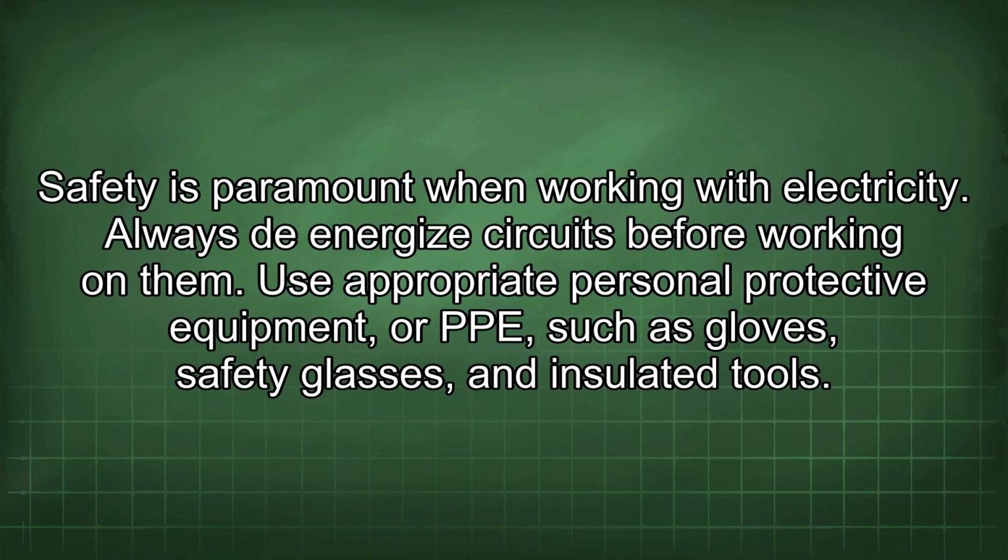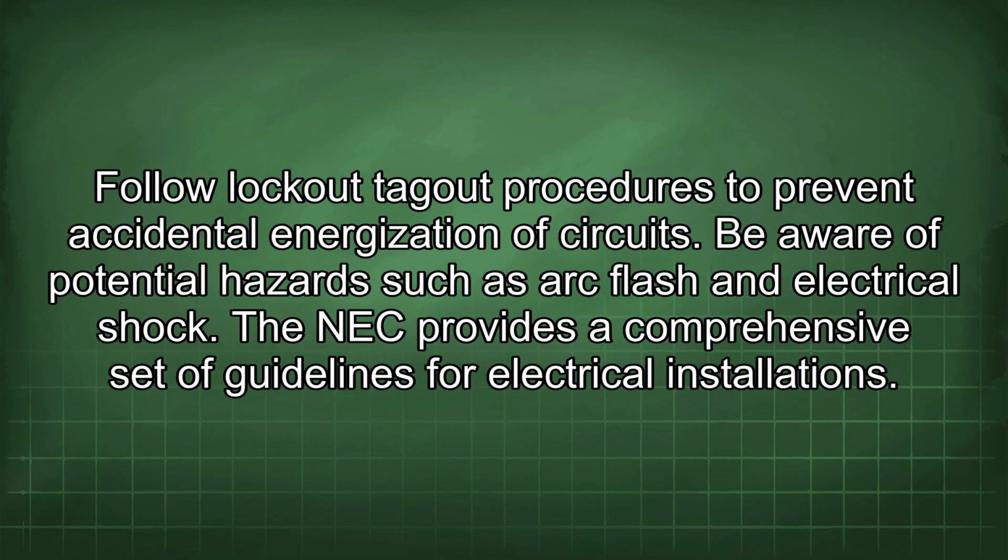Safety is paramount when working with electricity. Always de-energize circuits before working on them. Use appropriate personal protective equipment, or PPE, such as gloves, safety glasses, and insulated tools. Follow lockout-tagout procedures to prevent accidental energization of circuits. Be aware of potential hazards such as arc flash and electrical shock.